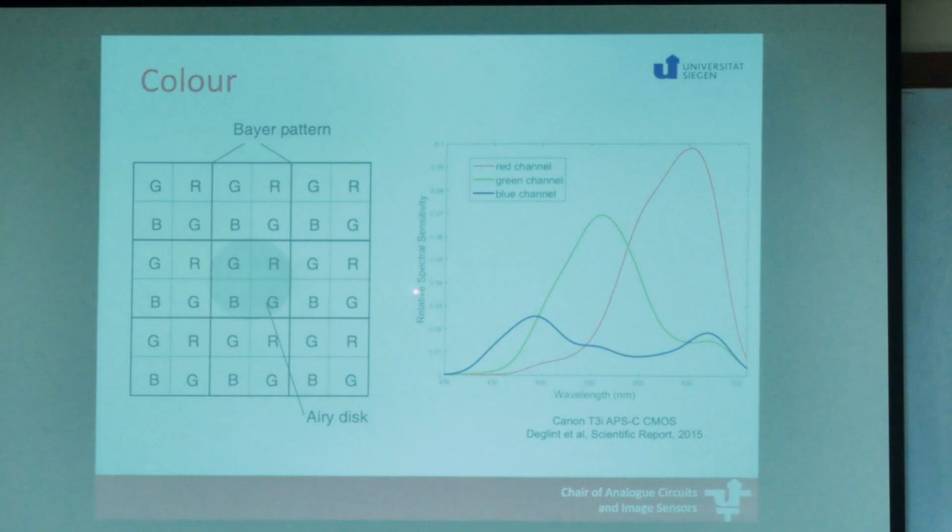The other problem arises, let's look at the green centered pixel. So I want to find red here. I only have 2 reds nearby, there's no red on top. So when I was at the red pixel, to find the green value of that pixel, I had 4 pixels to average. Here, I only have 2 red pixels to average. Am I making sense? Not making sense, stop me.